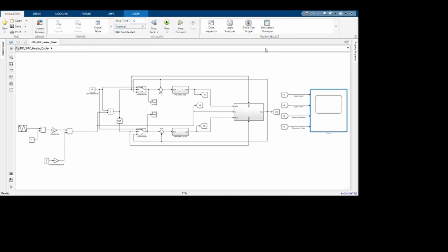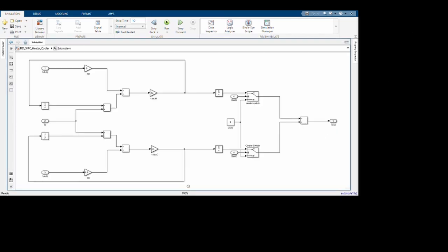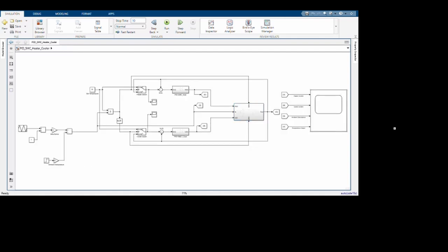As you can see, the ambient disturbance stays the same, but in this case our cooling control is not so extreme. We set a very small difference of temperature, so obviously it requires a very small output. Actually, it requires a negative output to sustain this temperature. The reason is that our plant model behaves such that the cooling gain is subtracted from our input temperature, and that gives us a cooling effect. So that gives us a first order differential equation.